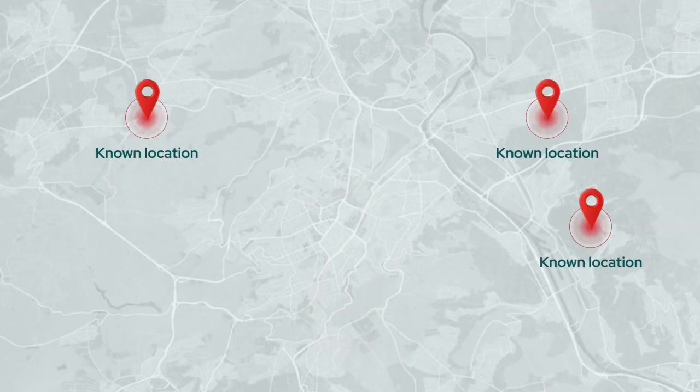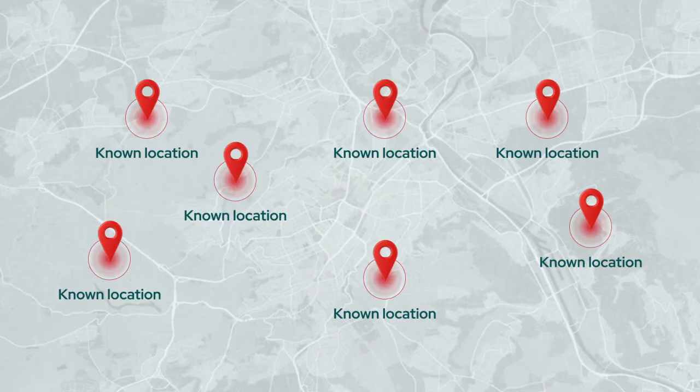So that's essentially a way for us to tell the drone data processing, hey, my drone I know is actually out by a meter when it comes to capturing the data, but here are some known coordinates that I captured with a base station where I'm quite confident about their positions, and therefore you can take these as an extra input and give me a more accurate drone map or model. And by accurate, I mean positioning in the real world.